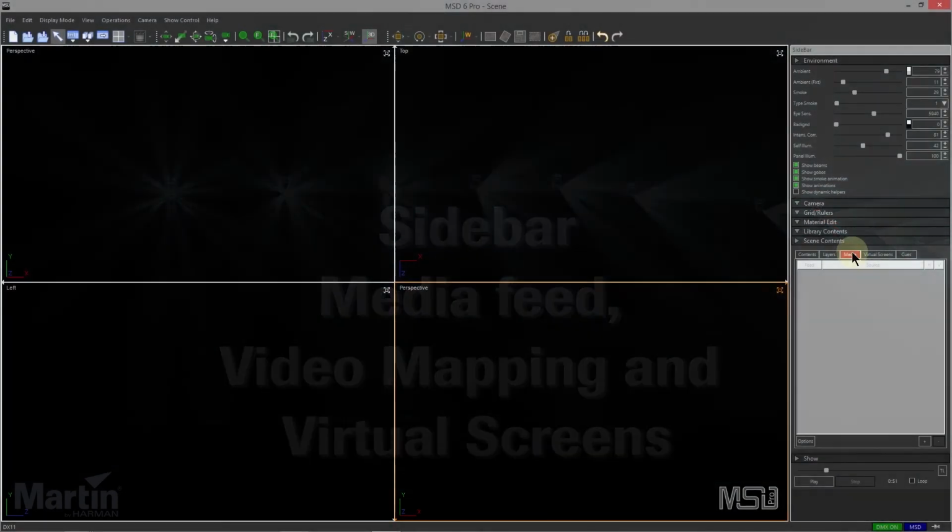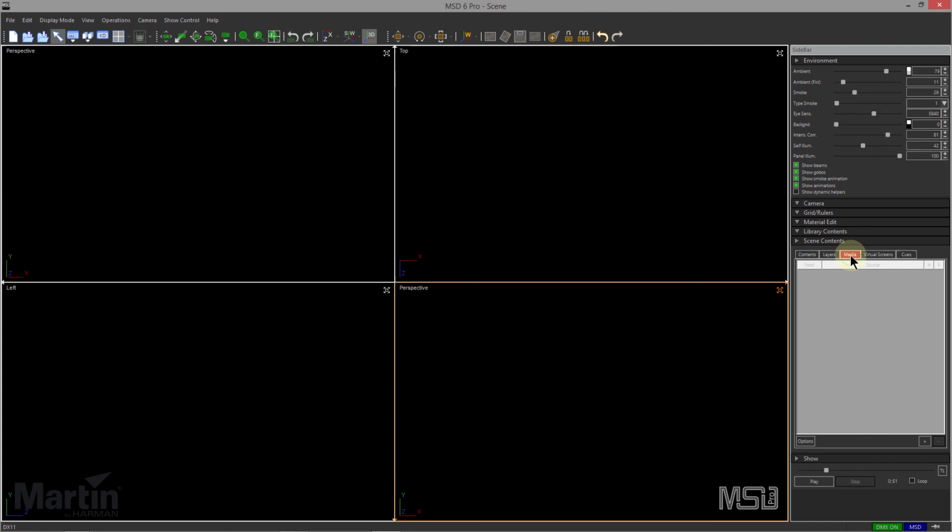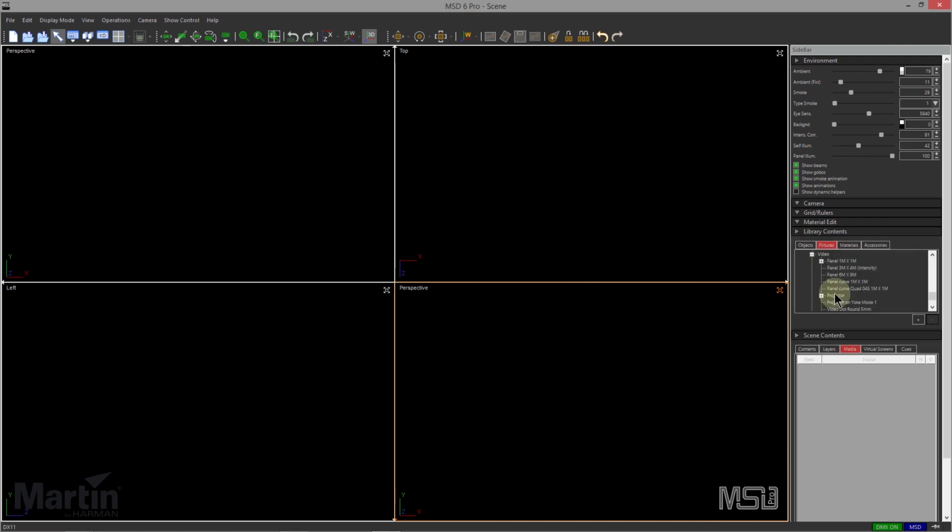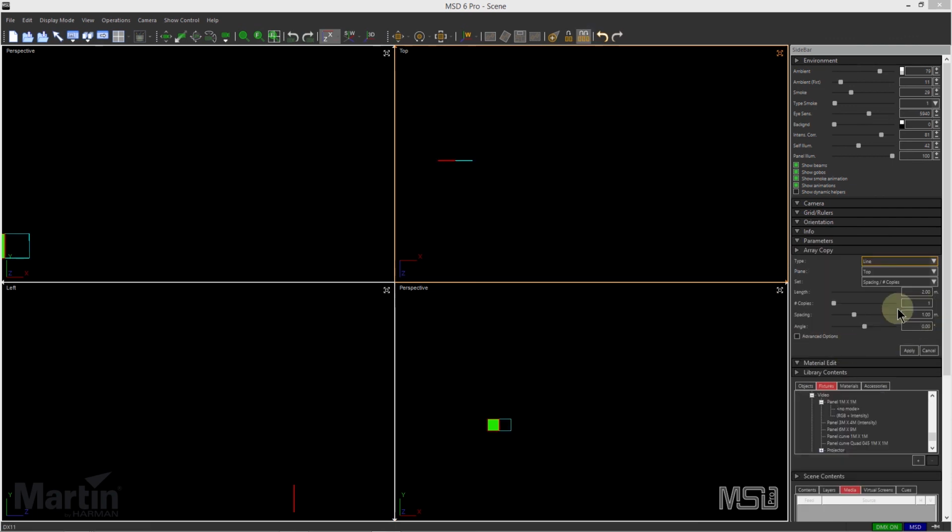For the next part, I'm going to use a new scene, and this is to show how the media works. The media is used to create feeds for video screens. So first, let's go to the library content in the video. We're going to take, let's say, a 1x1 meter video panel. We'll drop it here. Let's copy it a few times.